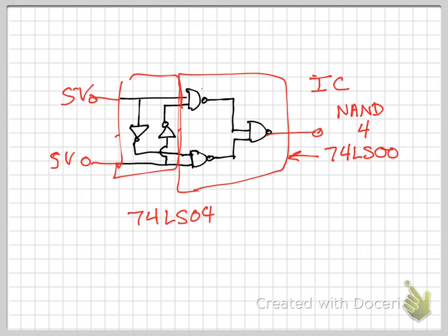The last part of the lab is a chip that has a neat function. I've always found it kind of neat and useful. It's called a multiplexer. The multiplexer we're going to use is an 8-input multiplexer. You can have 8 different inputs, and then you simply give the multiplexer a digital address. You tell it which of the inputs you want to go to the output.